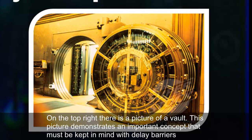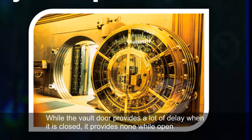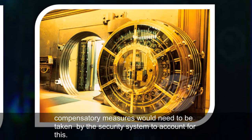This picture demonstrates an important concept that must be kept in mind with delay barriers and physical protection system design. The daily operation of the facility must be considered when installing delay barriers. While the vault door provides a lot of delay when it is closed, it provides none while open. The vault door is likely too heavy to be opened every time someone enters the vault. If it is left open during normal operation hours, then compensatory measures would need to be taken by the security system to account for this.